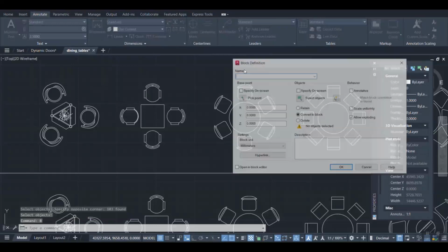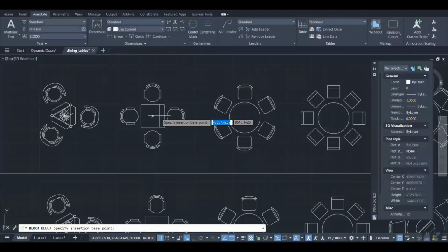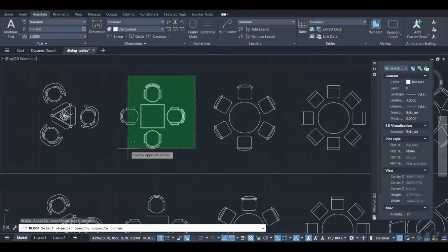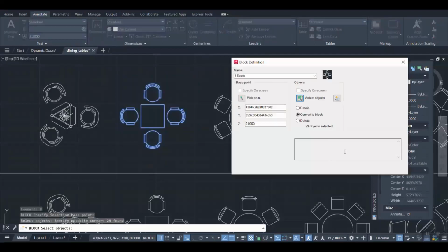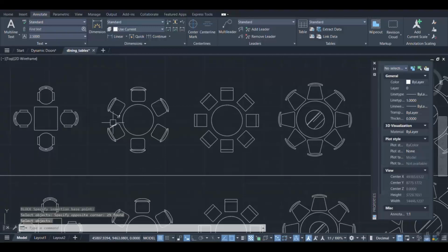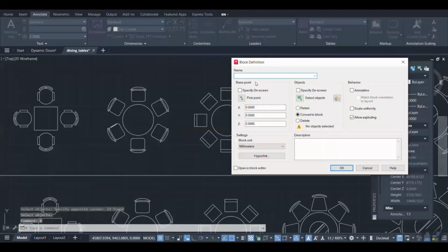First of all, you need to convert everything into blocks. That's the first part of my job. I think that is very easy, you know how to create blocks right away. Once it is a block, it will help you make a visibility, because while selecting inside visibility, you have to select with a single selection node.